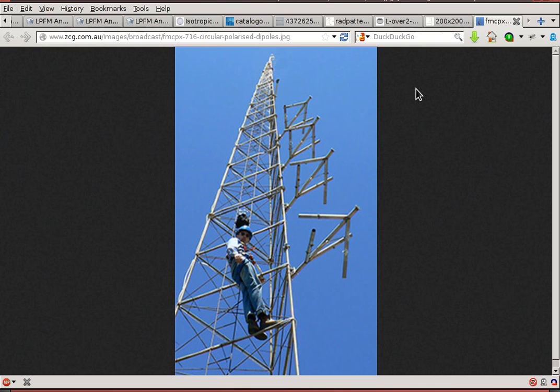They range from not terribly expensive to very expensive, and the calculations that you need to do to supply with your application to the FCC are quite sophisticated. It's beyond what RFree can do. If you're going to need to go that way, if your prohibited zones are just too large to manage in the site that you have, and you need these special antennas, contact an engineer that's used to doing this kind of work.